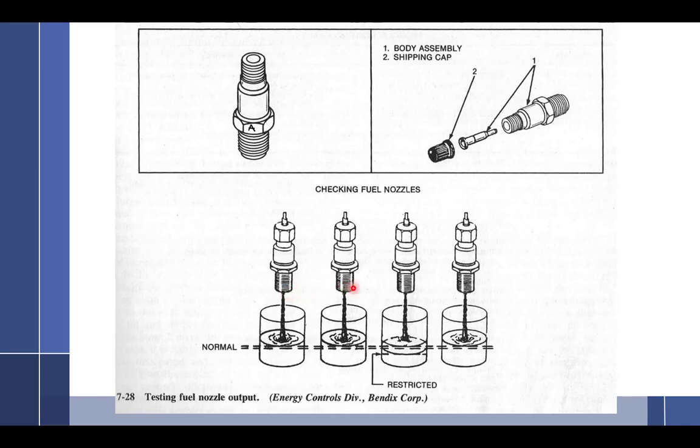So what am I going to be testing with this? Am I testing the integrity of the servo unit? Not too much. It's if the servo valve is open on the spring, that's all you're really going to test. You can look for other things, like fuel running out of the impact tubes, which will tell you you've got some leaky seals or diaphragms. And if you have one of them that's a little different, let's say this one right here didn't have quite as much, then that means the jet is plugged. Jets just plug, and that happens. Or it could be a kinked line.